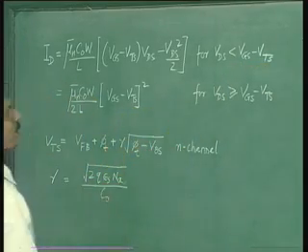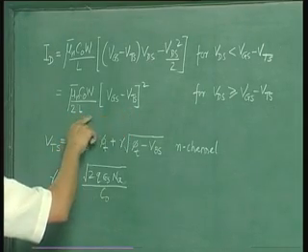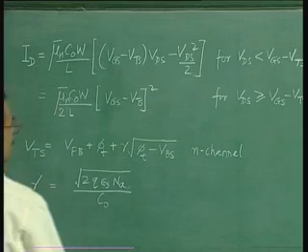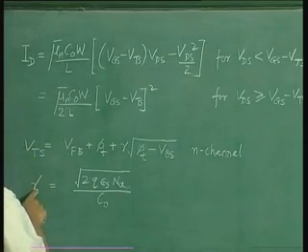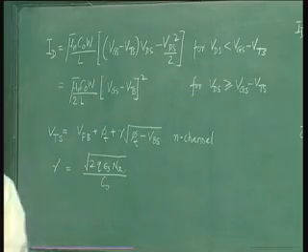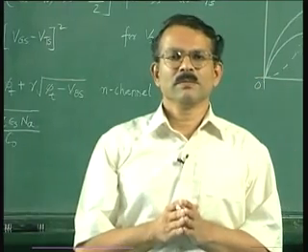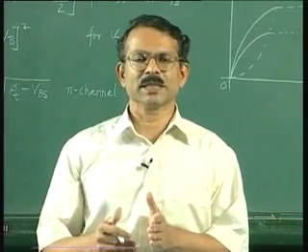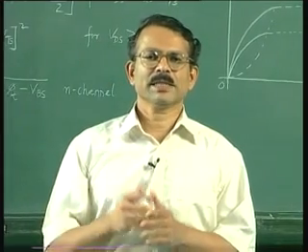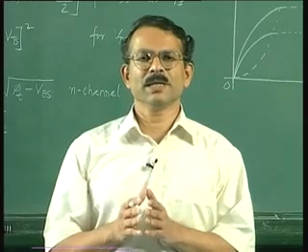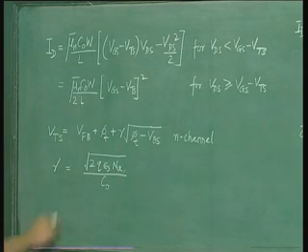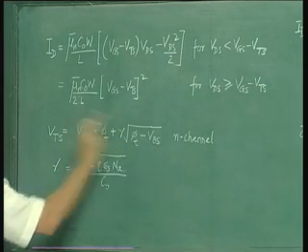So once the transistor is in saturation, according to the square law model, the current is constant at this value, which is obtained by substituting VD sat for these two VDS terms. And these are the expressions for the threshold voltage and the body effect parameter which enters into the threshold voltage. Now this threshold voltage is with respect to the source. Please recall that in the MOS capacitor discussion and also in the early stages of derivation of the MOSFET characteristics, we have always considered all voltages with respect to bulk, and therefore the threshold voltage expression was with respect to the bulk. Whereas in practice when you use a MOSFET, the source is normally the common terminal, and therefore here in these equations we are using all the terms with respect to the source. This equation also includes the body effect, as you can see from the VBS term coming here.